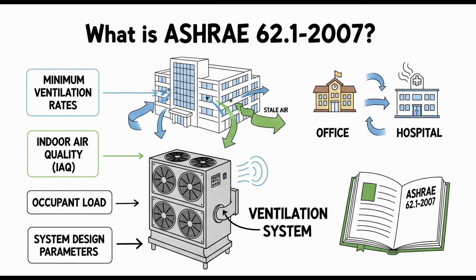Pretty much. You identify the contaminants, figure out where they're coming from, the sources, and estimate how much is being generated, the emission rates. Then you set specific target concentration limits for those contaminants. Where do you get those limits? You look at guidance from cognizant authorities like EPA, maybe OSHA, World Health Organization. Appendix B lists a bunch of sources, but also cautions that you shouldn't just blindly apply industrial workplace limits to a general office population, for example. Okay. And you still need that 80% satisfaction goal, too. Yes.